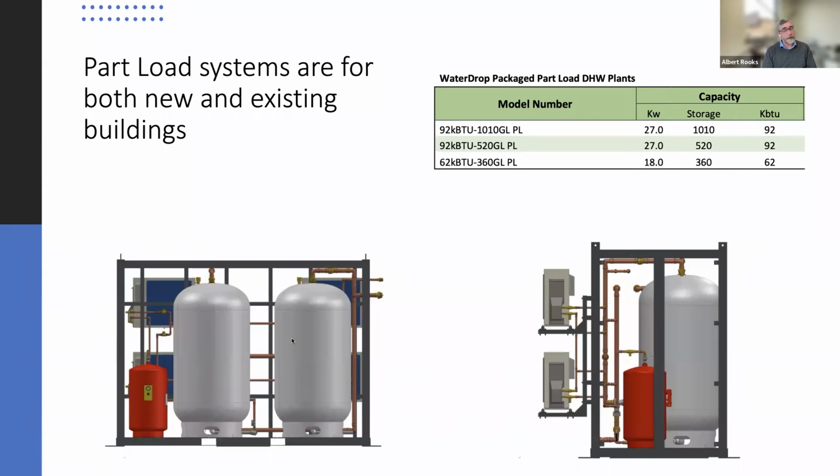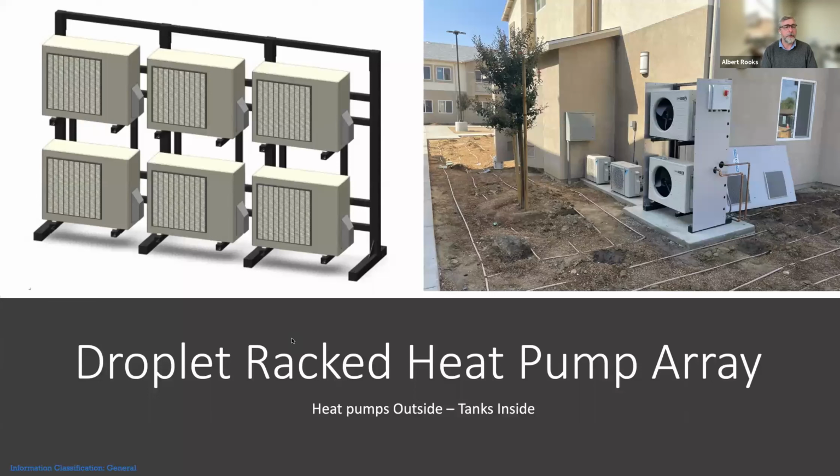And now the existing gas boiler or whatever infrastructure is there, maybe it's a little bit updated and the recirc pump's a little better because you got the odd opportunity to fix it. But in any case, now we're contributing ahead of the load of that building. If a boiler just sees incoming water temperature in conditions that it wants, it doesn't need to fire up, right? So that's a way we can reduce the GHG. So that's a part load system. That's a real thing.